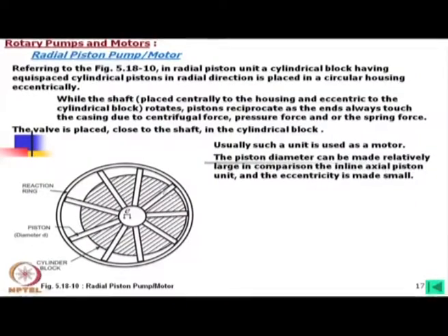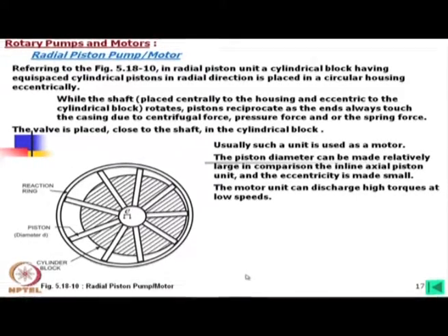Do you understand my point? For the same number of pistons, as we can increase the piston area, the volume will increase, but due to the eccentricity, stroke length will be very less. More area means it can generate more thrust, so more torque. So, these are usually used as low speed high torque hydraulic motors.